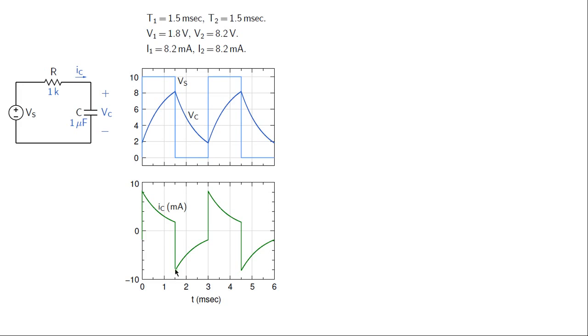What about delta, this discontinuity? If you recall, that is expected to be V0 divided by R, where V0 is this voltage, 10 volts, and R is 1K. So delta should be 10 volts by 1K or 10 milliamps. And this is indeed 10 milliamps, the same height as this height here. And this is also equal to delta, that is 10 milliamps.